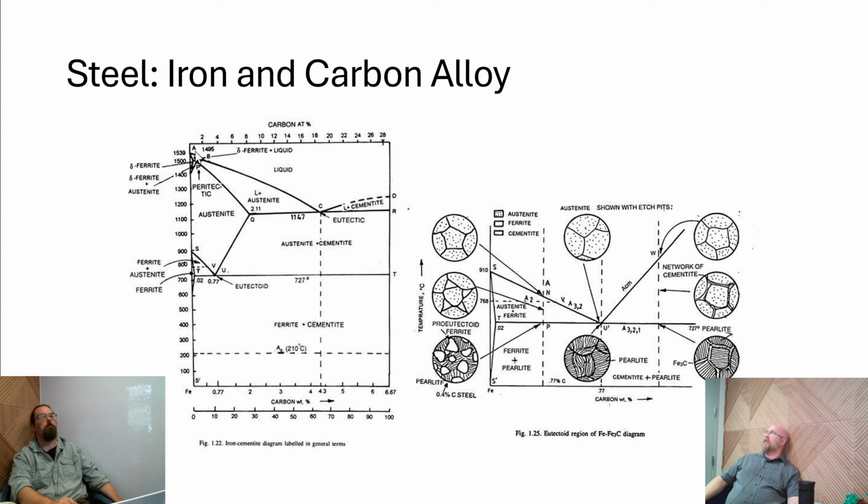And then if you look at that dashed line in the middle there, where we have an arrow pointing and saying eutectic, that is a eutectic point. This is an equilibrium that occurs, and basically because it's a lower melt point at that mixture, it wants to reach that equilibrium when it hits that temperature. And you'll notice that is a lot lower. That's at 1100 C, approximately. 1147, it says on there.